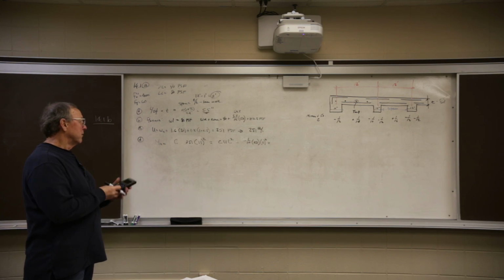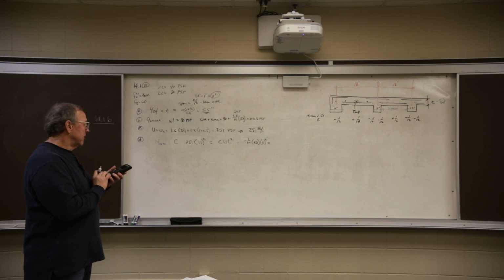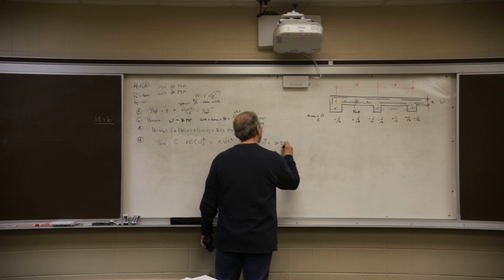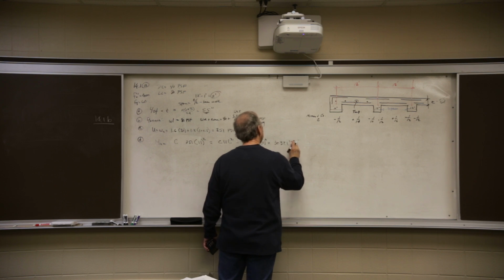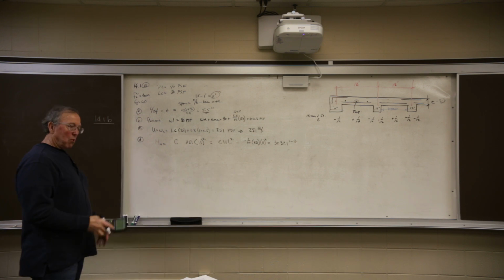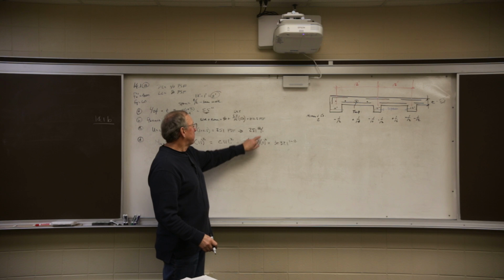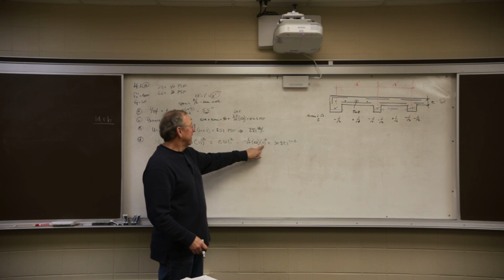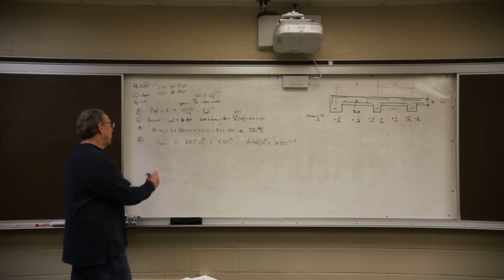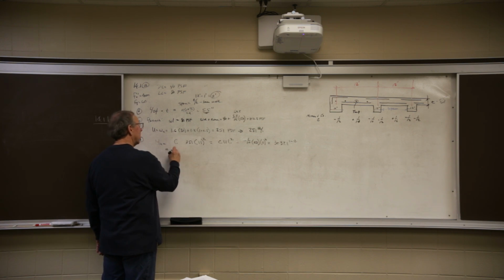So I'm going to take 251, which is little w u, multiply it by 11 squared, and divide that by 10. That's 3037.1 foot-pounds. Why is it foot-pounds? 251 is pounds per foot, that is feet squared, and feet squared times pounds per foot gives me foot-pounds of moment. Okay, so there's the moment.